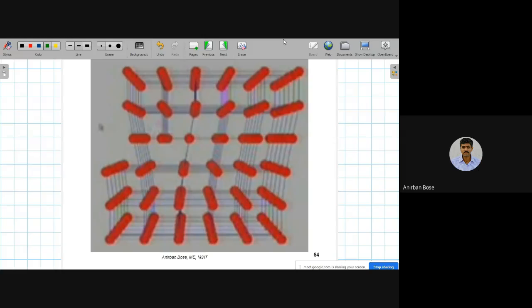Now, dislocation line, that means the FE line, that means the edge dislocation line vector. So the motion of dislocation will be perpendicular to that line T. So that line will move in this direction. This is the idea, that EF line will move in this direction. So let us try to visualize how it will move.